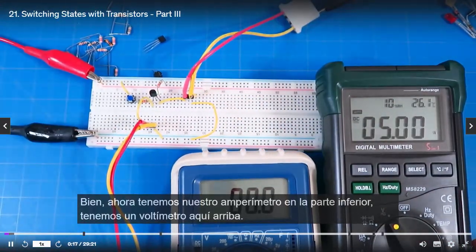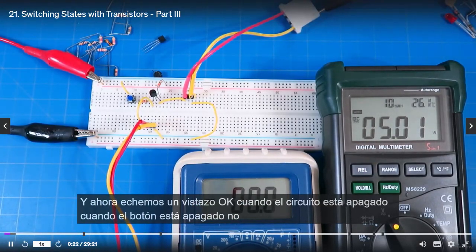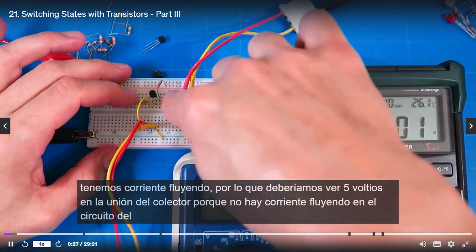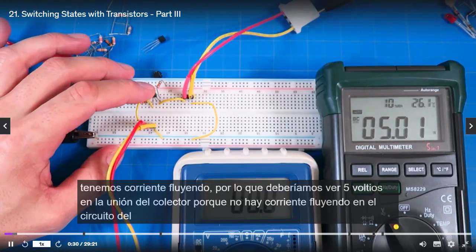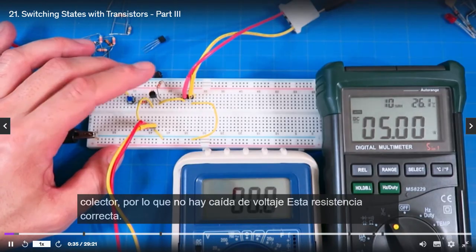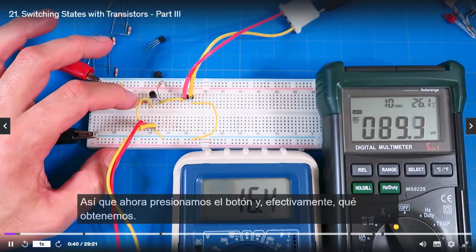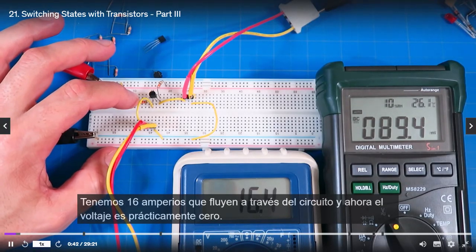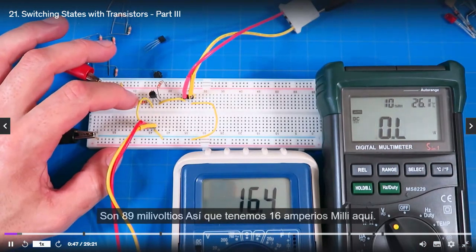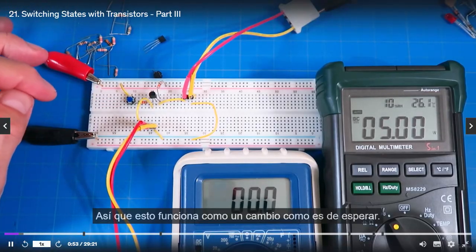Now we've got our ammeter at the bottom and our voltmeter up here, so let's take a look. When the button is off, we've got no current flowing, so we should see 5 volts at the collector junction because there's no voltage dropping over this resistor, right? Now we press the button, and sure enough, we have 16 milliamps flowing through the circuit, and the voltage is practically zero. It's 89 millivolts. So this is working as a switch as we would expect.